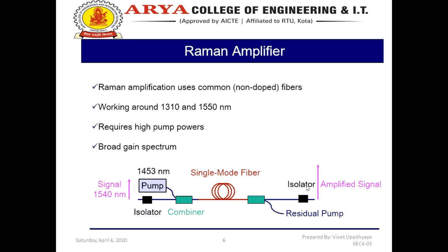So, the Raman amplification uses common, that is non-doped, fibers working around 1310 and 1550 nanometer. It requires high pump power and has a broad gain spectrum.